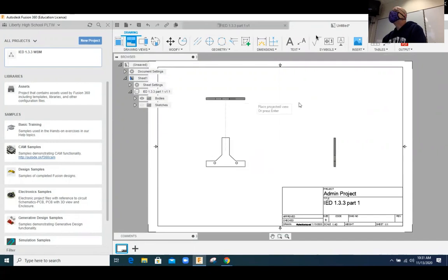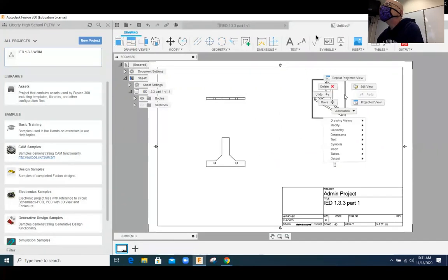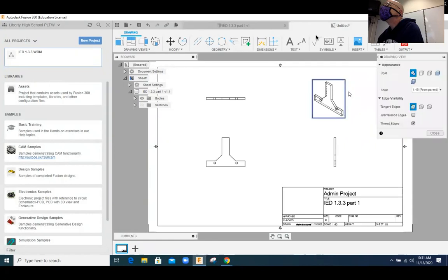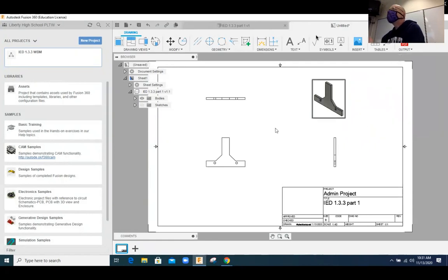And you're probably thinking, what is that? That's the top, front, and side of the object. Here's the isometric 3D view. Isometric 3D has to be, edit the view, has to be shaded, cannot have any hidden lines. And there, that looks nice.